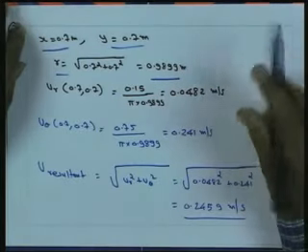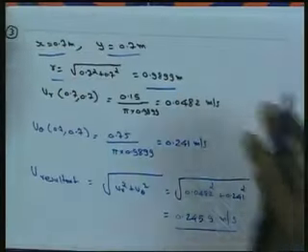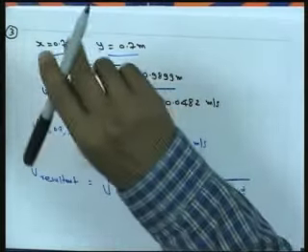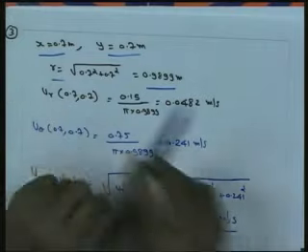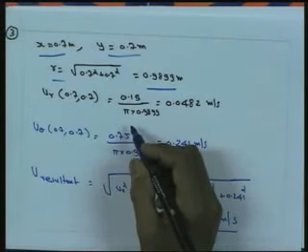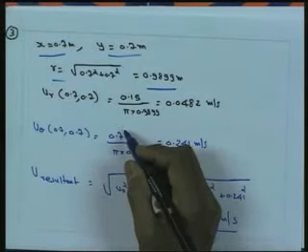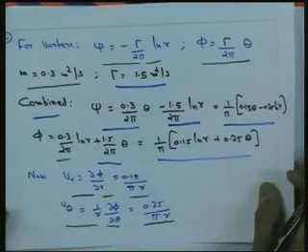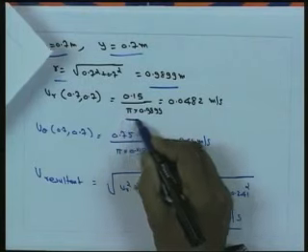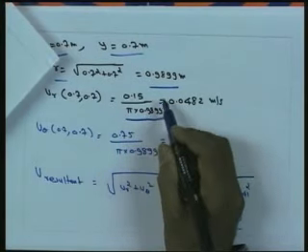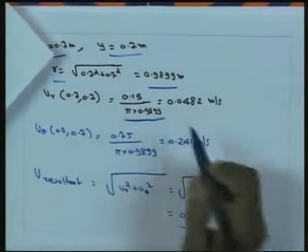So now we can obtain the value of the radial velocity at (0.7, 0.7). Since the expression for radial velocity we obtained is Vr is equal to 0.15 by pi r, this is equal to 0.15 by pi into 0.9899, which is the r obtained.